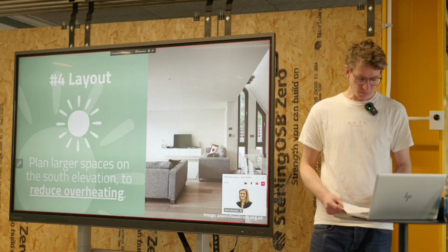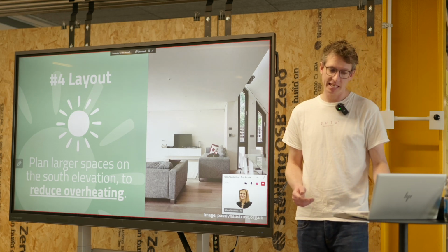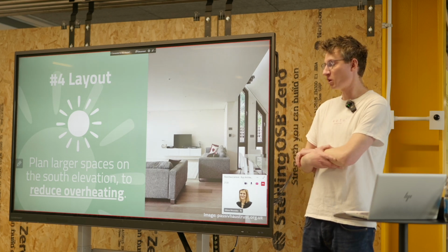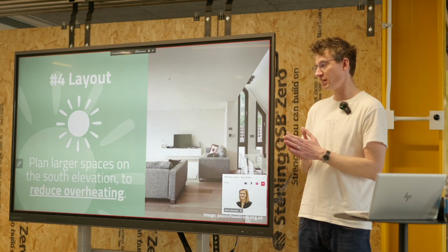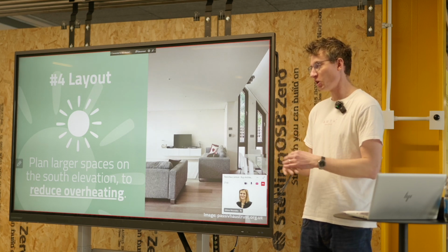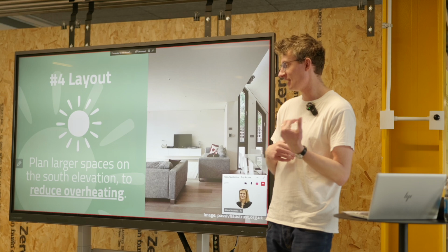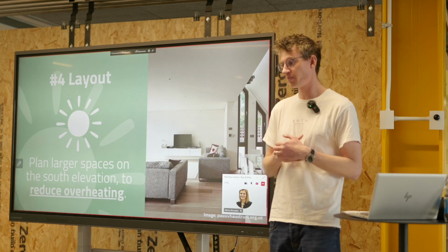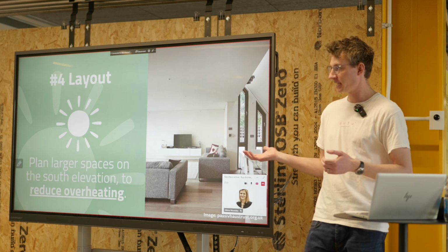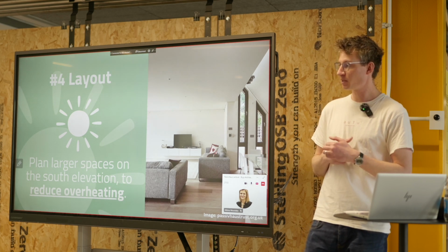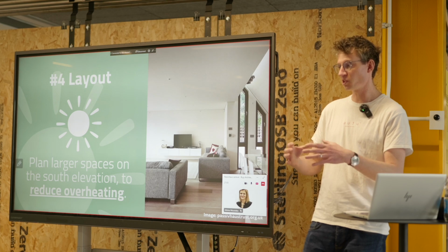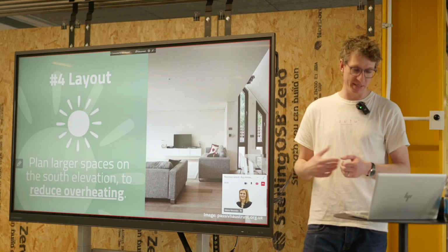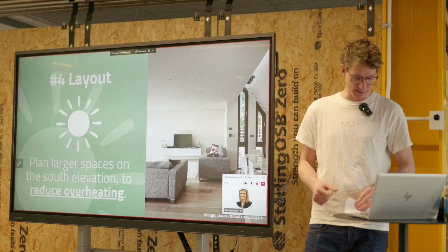Finally, another thing to consider in terms of layout is trying to mitigate heat loss in the winter through opening of doors as well. So your front door, ideally you wouldn't necessarily want that to be opening, but a bit like you were talking earlier, Fadi, in the winter you perhaps have a lot of heat loss through the front door. So let's say you're designing a domestic property, you might consider a vestibule or a porch or some kind of shelter at the front door, so you're not having huge amounts of heat loss from the front door, particularly not opening onto a big open plan space.